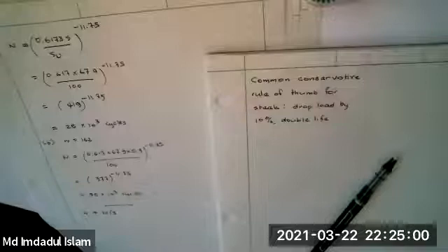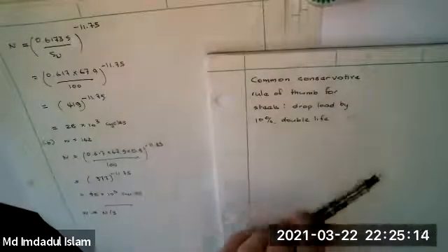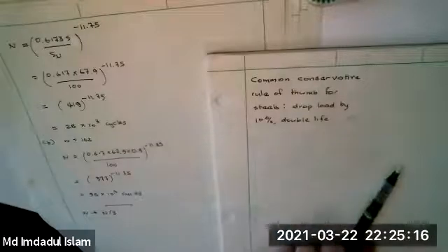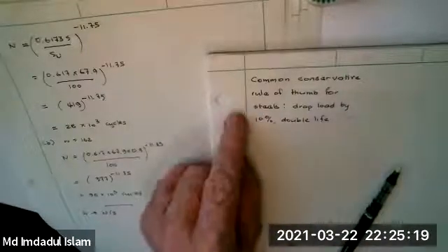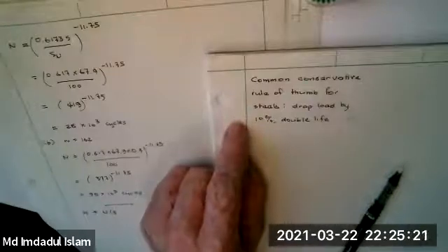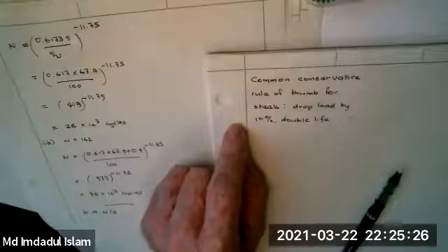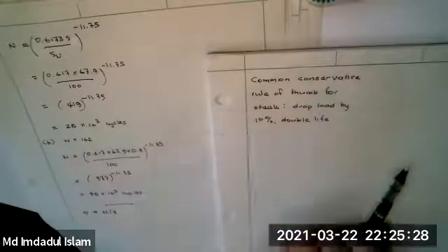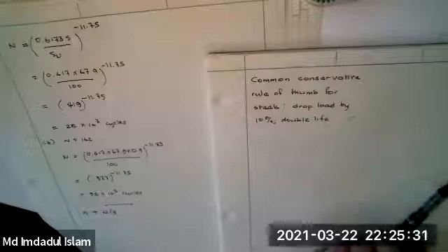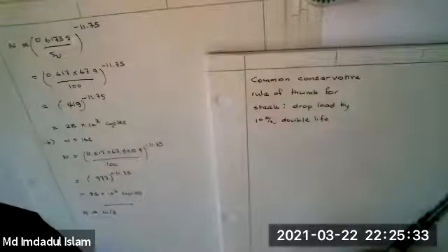Now, eventually you want people to test these things and find out. You test the existing ones, and you get their life, and then you test the new design rods. You don't just rely on a rule of thumb. But if you want to redesign something quickly to get increased life, you use this rule, and you're almost certainly being conservative. And quite often, if things are designed for people's lives and you get a factor of 4, that's going to be enough. In fact, they have adopted that design of that Harrington rod now in practice.